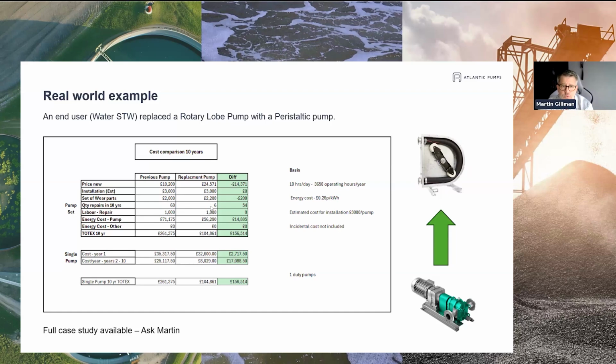Incidentally, what was also quite interesting, and this was all officially verified, done with proper power data loggers and recorded: we put a power logger on both pumps, which ran side by side for a period of 7 days, and we found that one pump drew 7.4 kilowatts just to do the same thing, and the other pump just 5.6.